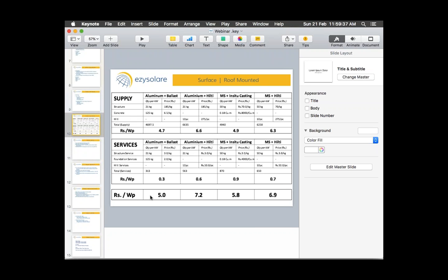It's kind of a hybrid between dual axis and single. Somebody is naming it a 1.5 axis structure. You can name it as a fancy thing, but it makes much more sense from the cost perspective. So you're saying on a 1.5 axis structure, especially if we are at higher latitudes, we give the structure a certain tilt, maybe 10 degrees, and then rotate it east to west. Yes.